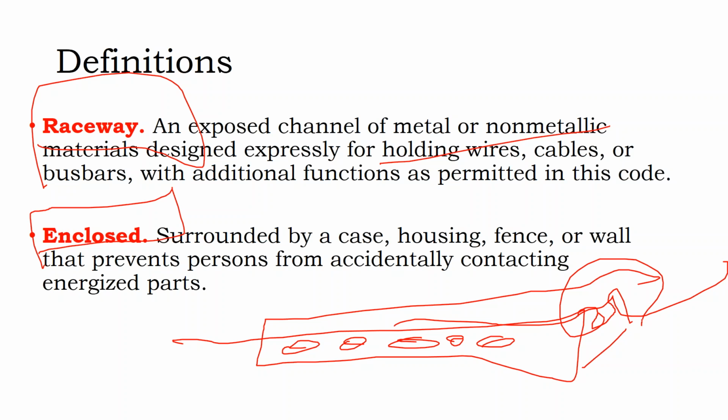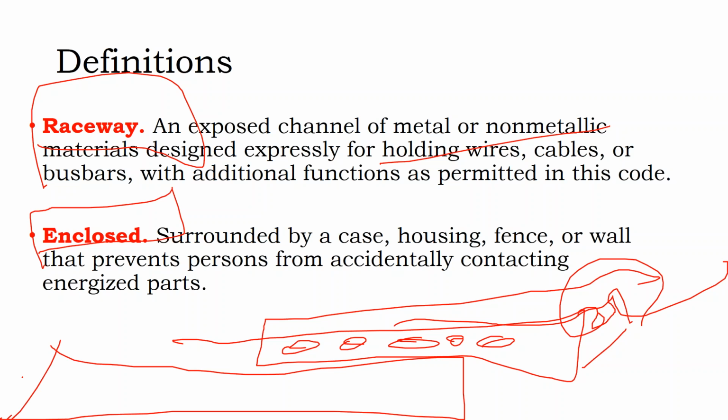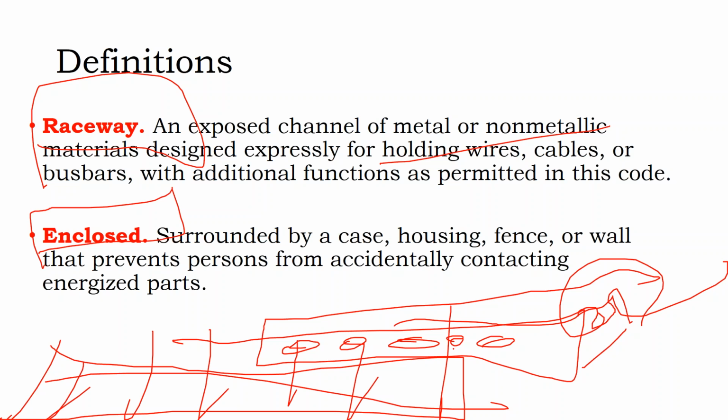It might be that your solar cables should not go into an enclosed raceway because they need airflow. So if you have a cable tray with solar conductors, it may be a ladder tray if you're up on the rooftop and using your high voltage solar cable, so that you still have airflow into it. But when you go inside of a building, you may have a different set of requirements. When you're inside a building, your DC conductors must be fully enclosed. And so what might work as a raceway up on top of a roof may not work inside of a building.